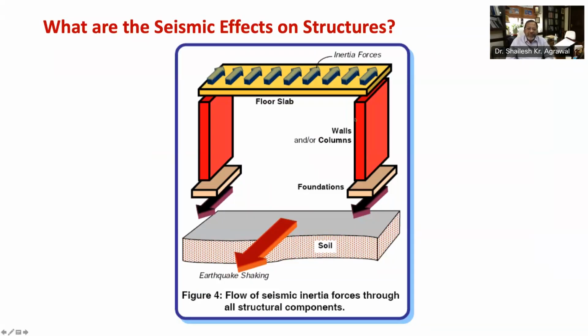Normally, the vertical elements, which are walls and columns, are the most critical elements in transferring these inertia forces. However, in practice or in traditional classical gravity load design, floor slabs and beams are normally kept thicker and heavier than walls and columns. Also, the walls are relatively thin and often made of brittle material like masonry. These walls are poor in carrying horizontal inertia forces along the direction of their thicknesses, and therefore they fail during earthquakes.